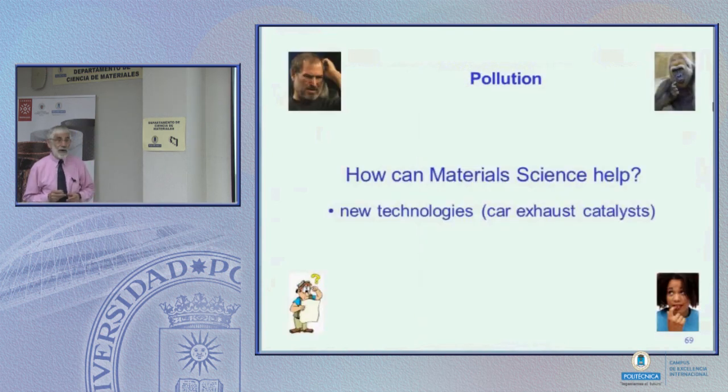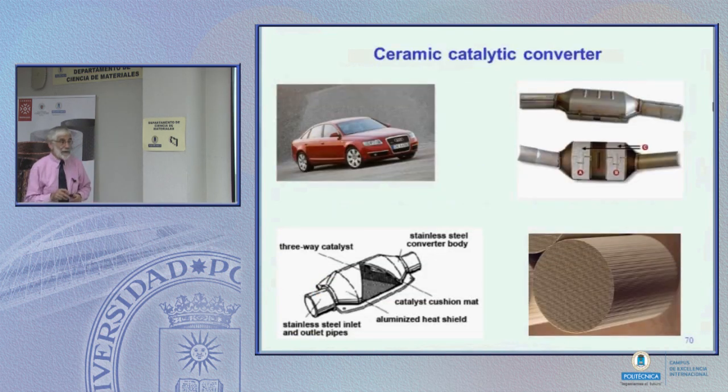How can material science help with that? Well, all of our cars nowadays have, underneath the car, the exhaust system where the gas is, and inside this, we have aluminium oxide, and on it are palladium and platinum. And that is a way of reducing some of the emissions, of making sure some of the partially burnt emissions are trapped and converted so that there is less pollution.